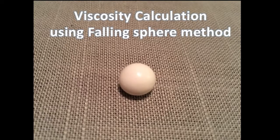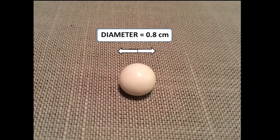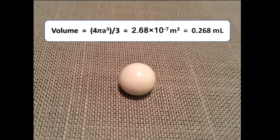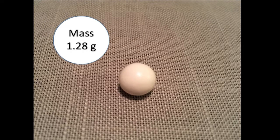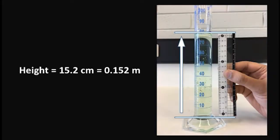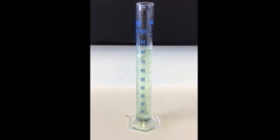We performed a simple experiment to calculate the viscosity of the product. A spherical ball made of marble was used in this experiment. Its diameter was measured and used to calculate the volume of the ball. Then the mass of the ball was measured and the density of the sphere was calculated. In the next step, the product was filled in a graduated cylinder and the height of fluid was measured. The marble ball was dropped into this cylinder.